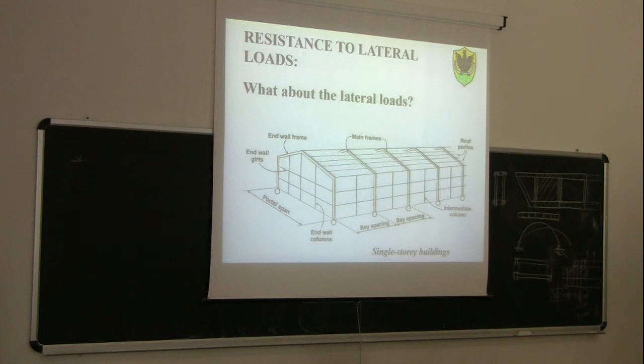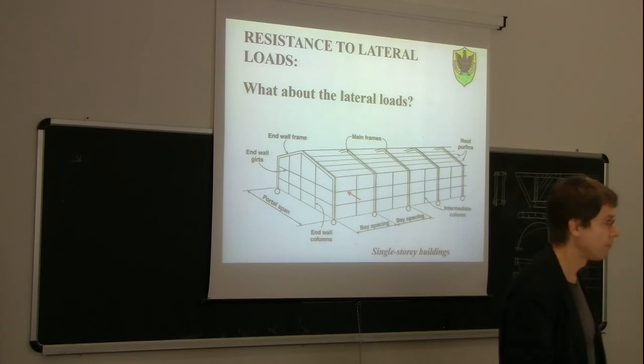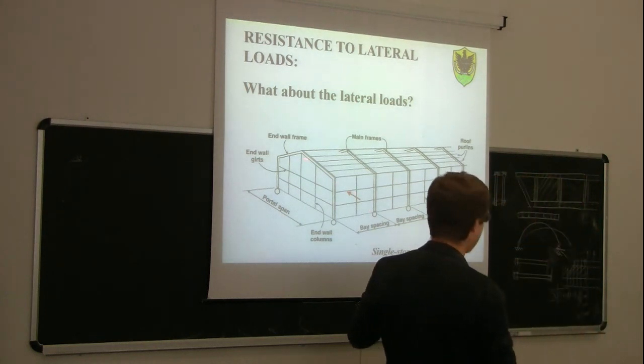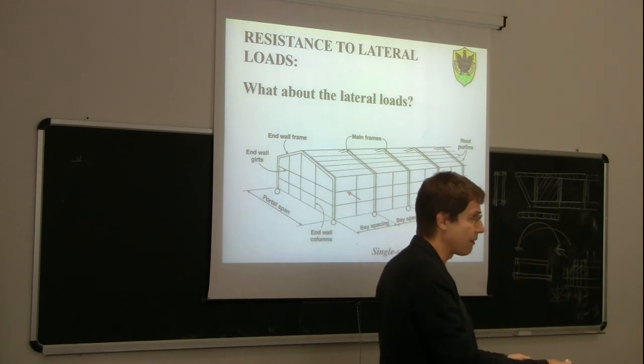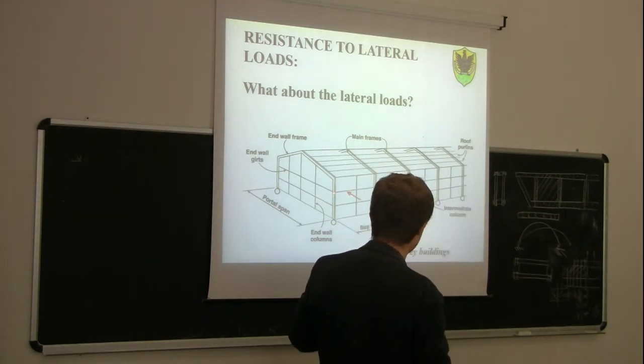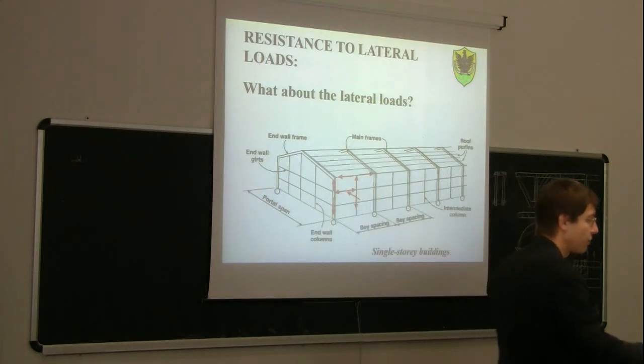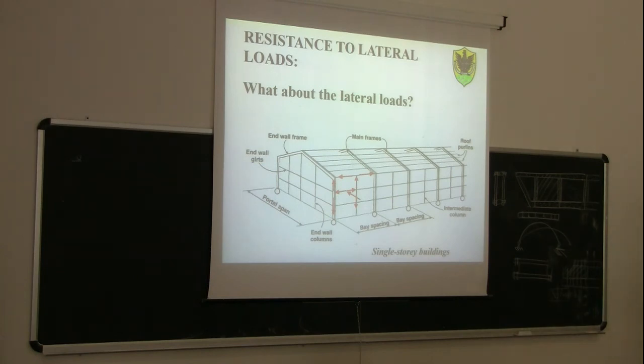Now for horizontal forces, horizontal loads, wind for example. If I have wind blowing in this direction, if I apply a horizontal point load on the lateral facade, can this load get its way down to the foundation? Yes, correct, because it is in the plane, parallel to the plane of the frame. So this one again will go probably one third here, two thirds on the other side, in some way. And then from the frame, as we said before, the frame is either two pin or three pin. Anyway, it can resist any lateral load. So this is okay.